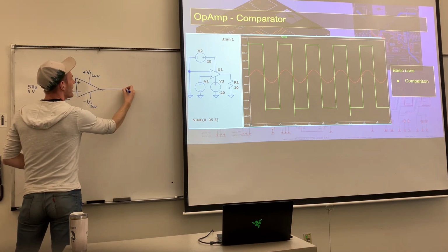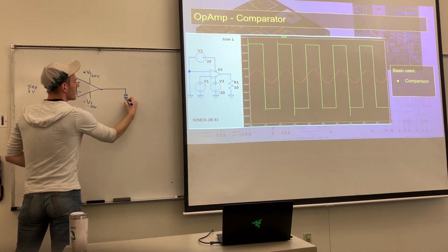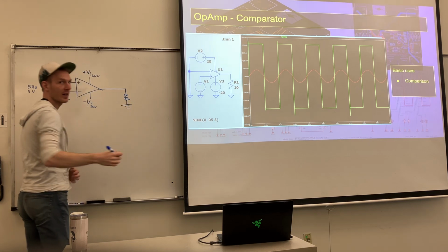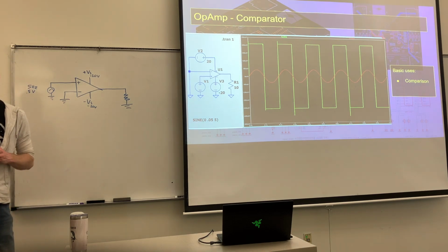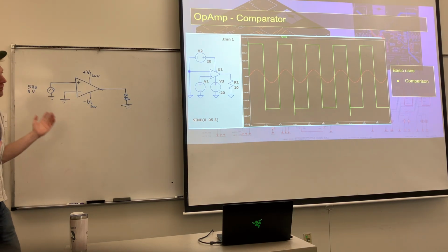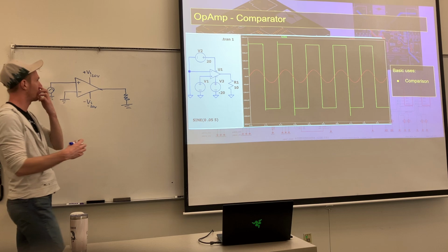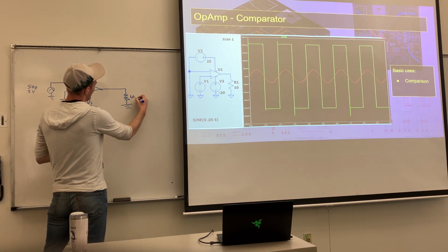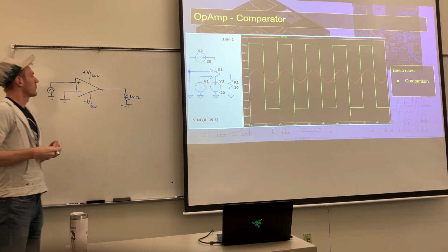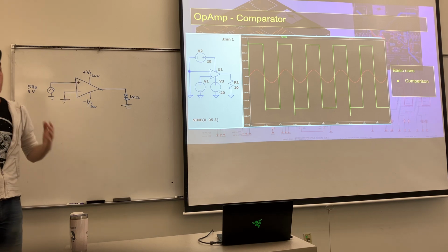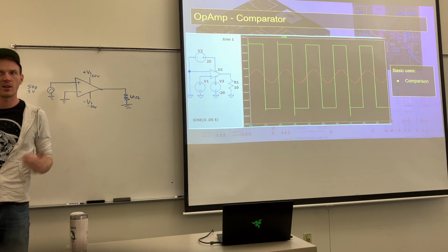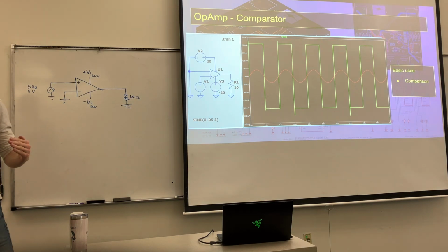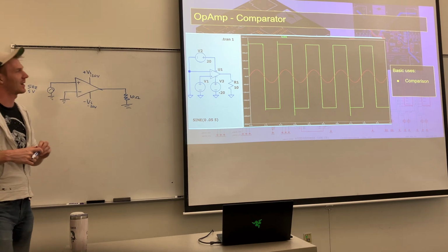And then we have it feeding some load. Most of the time for an electrical purpose, you just represent that via a resistor. You're saying, hey, it's doing work here, it is dissipating energy. That's effectively a resistor. We put it at 10 ohms for this one, but it's kind of irrelevant. And so a comparator, all it is doing is saying, which is higher, my inverting or my non-inverting, and whatever it is, I'm going to output the most of that I can, basically.